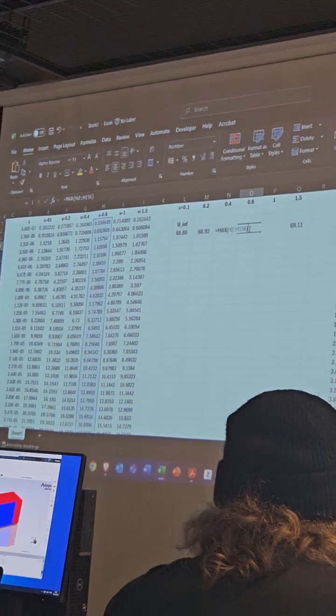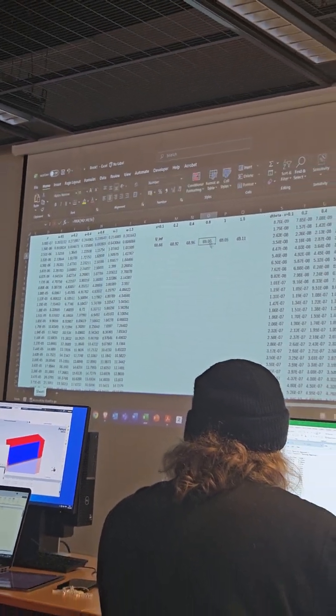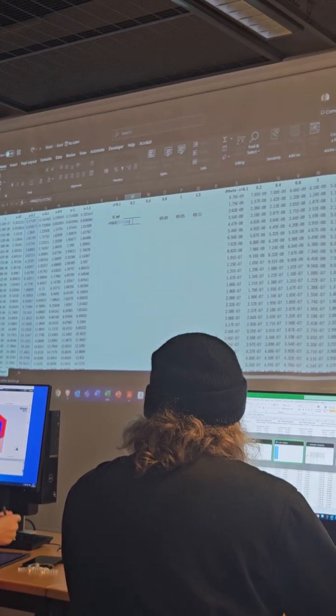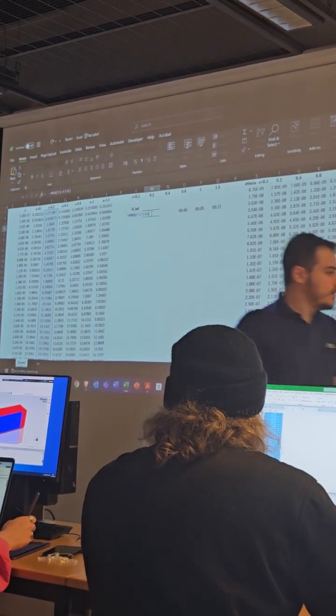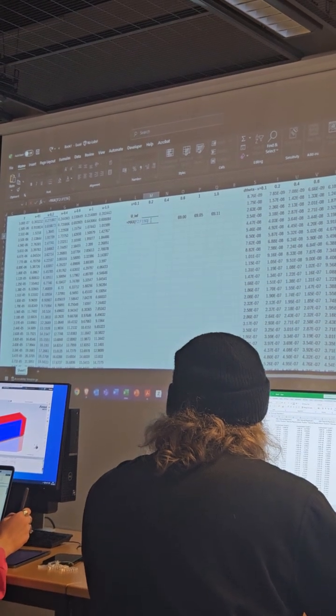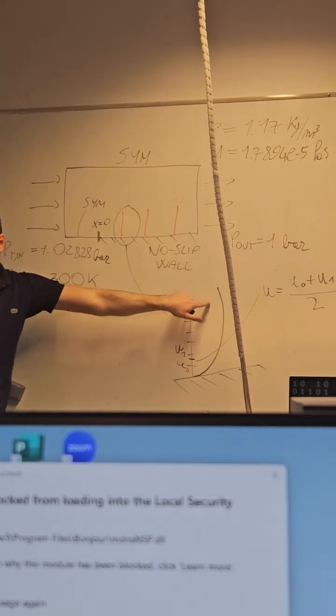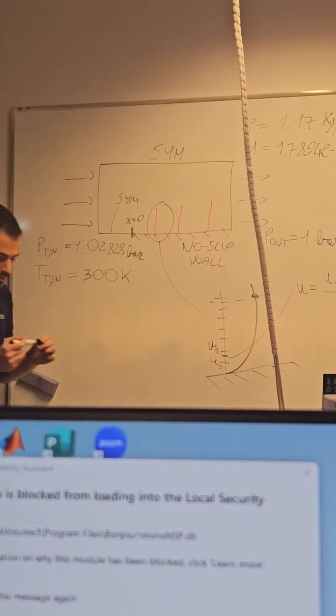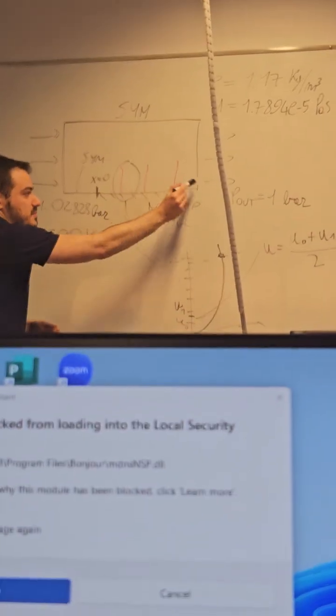Why not choose 0.2? The same. The 0.2 then is going to be the u infinite at 0.2. Okay. So we select the maximum value as the value of the velocity. Basically, this is your y. So if this is our line, basically what we have is something like this, our boundary layer. At the top you are in the free stream region. The Mach number is still constant, 0.2.